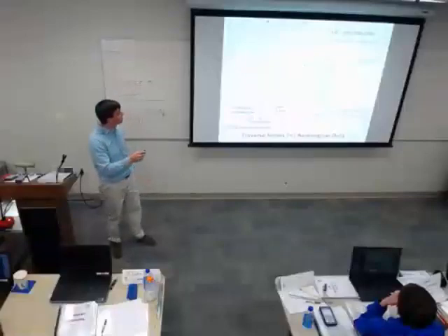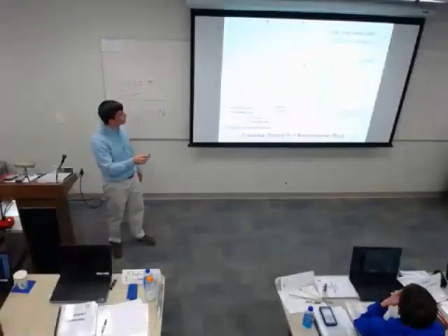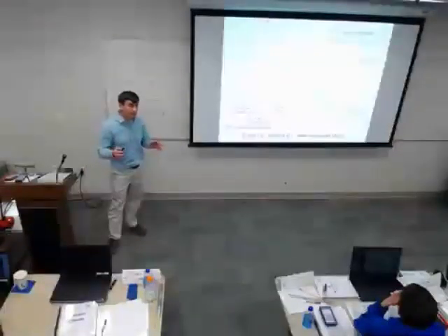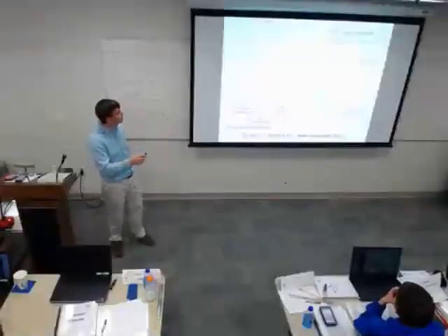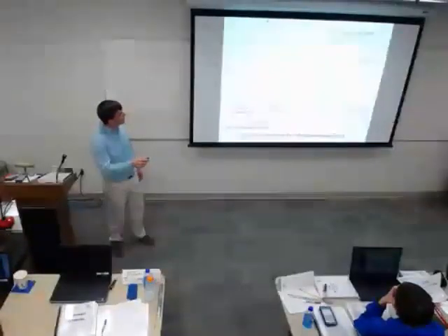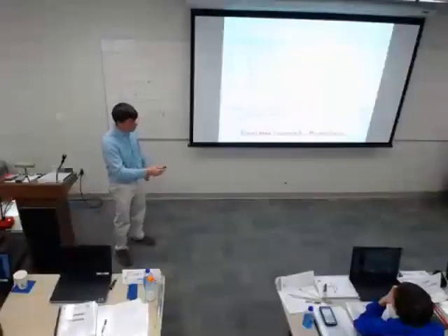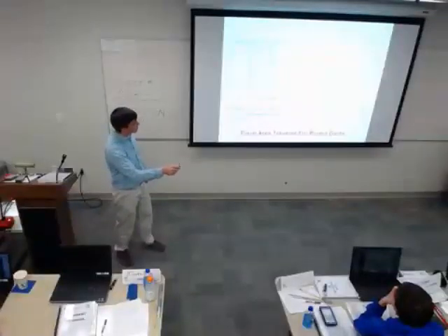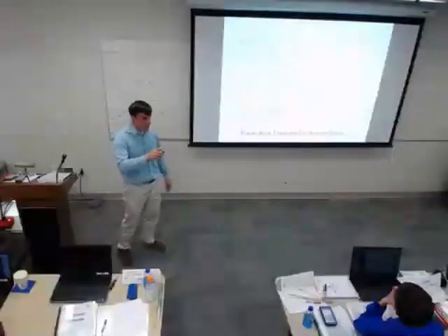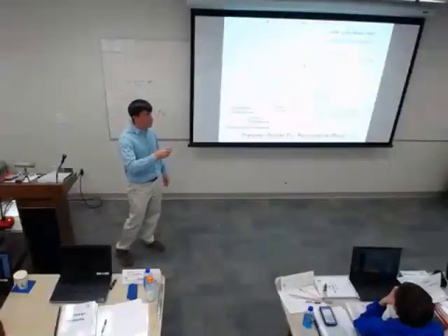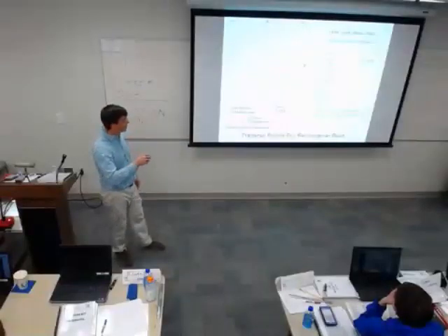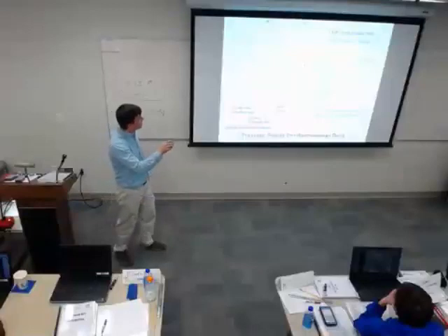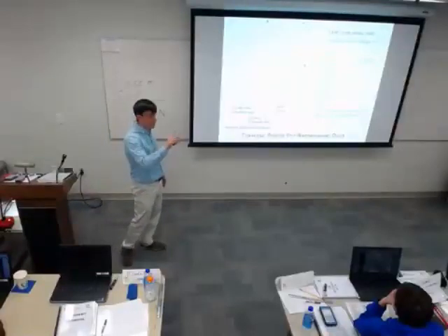And I'm going to basically do the samples through that duct. I'm doing an equal area method. I do the same thing for a round duct, and you'll see these are spaced a little differently, but I'm coming up with a velocity for equal areas within that duct.